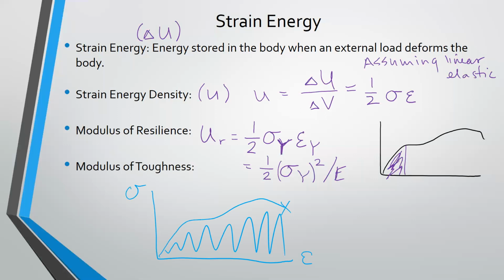I don't have a quick and easy equation for you because it's going to depend entirely on the shape of the curve, which is no longer a constant. With linear elasticity, it's always a triangle, but this could be elastic perfectly plastic, it could be bilinear, or you might have an actual curve that you need to numerically evaluate the integral of.